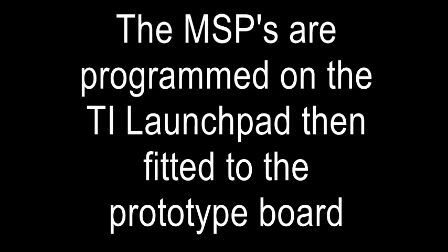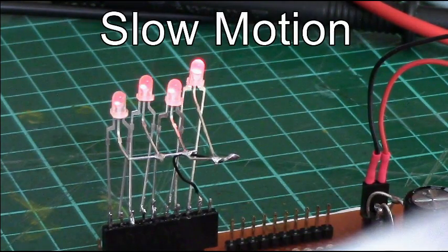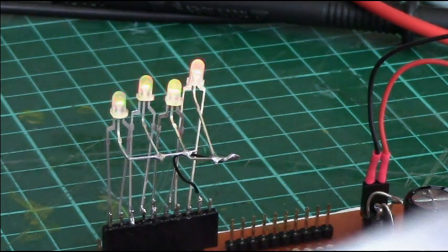It's important to note that we've programmed the MSPs on the Launchpad board, then extracted the chip and fitted it onto the prototype board. If for some reason we don't get an input from the A or B side, then the LEDs will cycle between red and green until correct signals are received.